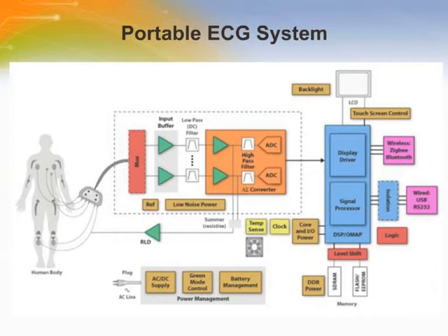The INA333 offers high 100 dB CMRR to reduce the 50/60 Hz line noise common to both inputs, as well as offering 20 microvolts of offset, keeping the measurement error below 2% on a 1 millivolt signal. Additionally, the 75 microamp supply current and 1.8 volt supply enables maximum power efficiency and extends the life of the battery.